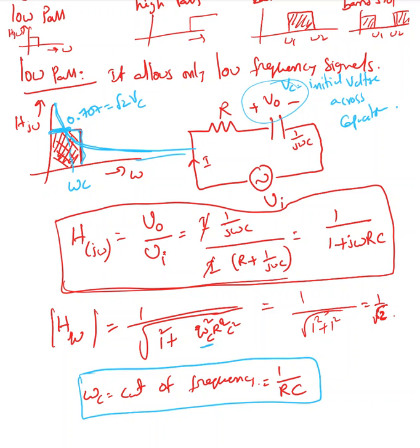I'm saying this is the low pass filter, but in reality with passive elements we cannot build a square or rectangle like this. The signal is going to go down exponentially in an RC circuit, because if you remember, a capacitor does not allow sudden change in voltage. At frequency 0, that's a DC supply, and the capacitor acts like an open circuit, so you will see the maximum voltage right there.